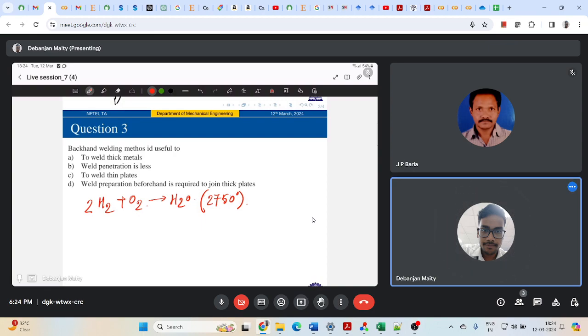However, it is impossible to obtain a neutral flame in your oxyhydrogen combustion just by some visual methods of flame adjustment, as we were explaining for this oxyacetylene flame, right? So the oxyhydrogen flame itself is visible, and there you cannot distinguish any kind of combustion zone.